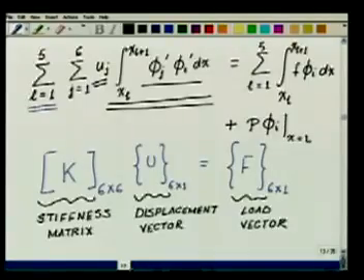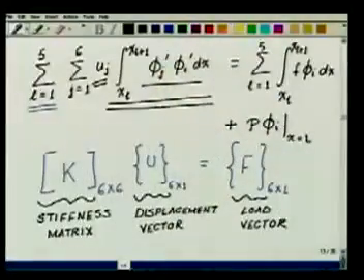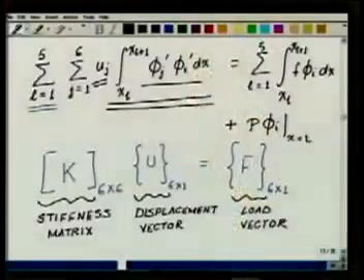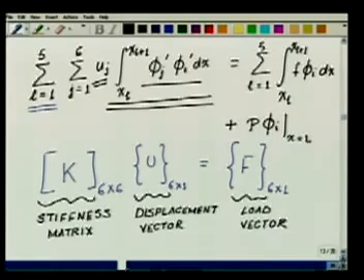So if I now want to find the entries of the stiffness matrix, it is very simple. Looking at this expression, we have I rows, which is 6 rows, and 6 columns. Rows come from substituting W with phi I. W equal to phi I gives us the ith row, and the jth column of the ith row comes out of these phi j.